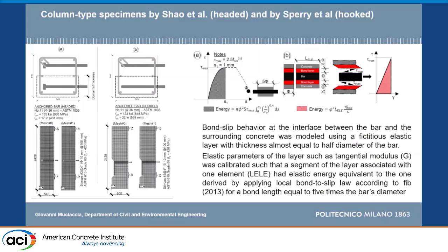So, helped by this, okay, we went on a little bit. We made this numerical analysis, checking, of course, mesh dependency, which can be quite interesting. In this case, just to show that we did not model this part because it was a monotonic test, and this part gave a lot of issues from a numerical point of view. So we took this out. And making this assumption of bond: since bond was not the main point, since unbonding was never reported, but we still want to capture a little bit the transfer behavior, we made this simplification.